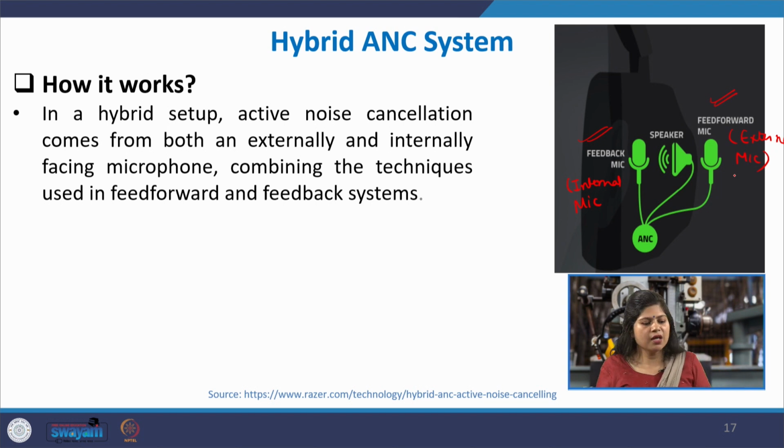And this is the headphone. So, it measures the noise just before reaching the ear. So, what is the ambient noise around the ear? Then the reference signal is created, and by the time that noise reaches the ear, cancellation happens. But there is also an additional mic present at the ear to see whether the perfect cancellation has happened or not. If it has not, it carries the error signal and adjusts the anti-noise signal dynamically by giving this feedback back to the ANC system, okay. So, whatever is there, some kind of error signal and adjustment happens to the already created anti-noise signal.